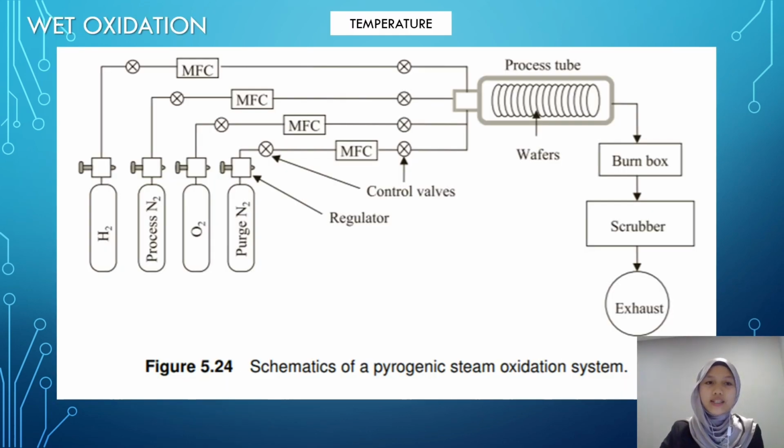According to the ATEC run card, wet oxidation is conducted for first field oxidation after wafer preparation. This shows the flow of the wet oxidation. Firstly, it is idle with purged nitrogen, and then it is idle with processed nitrogen. Afterwards, oxygen is ramped up, and the wafer boats are pushed into the process tube. Temperature is increased until stabilized, and oxygen is increased until stabilized.